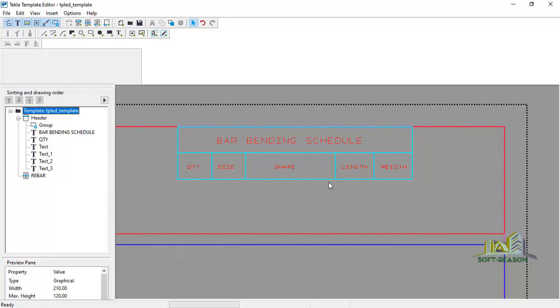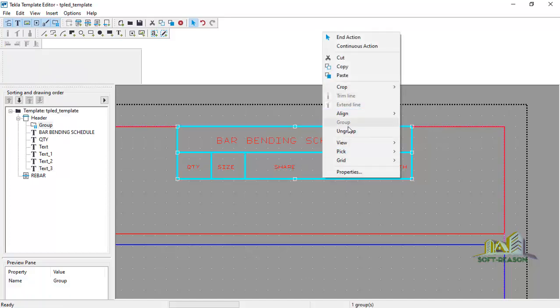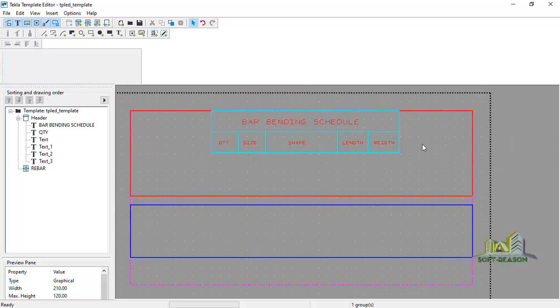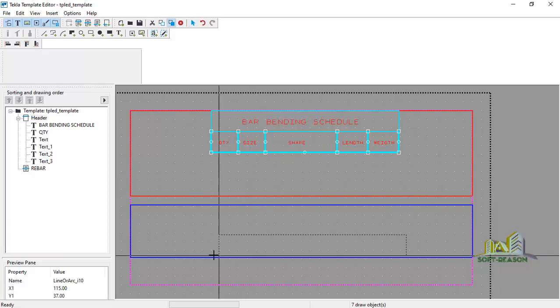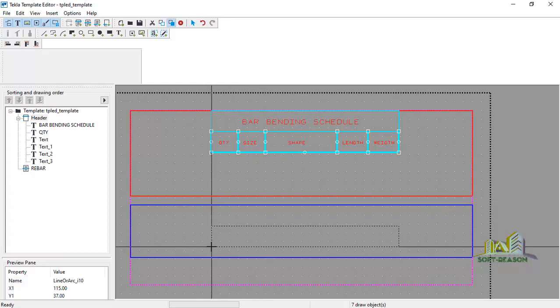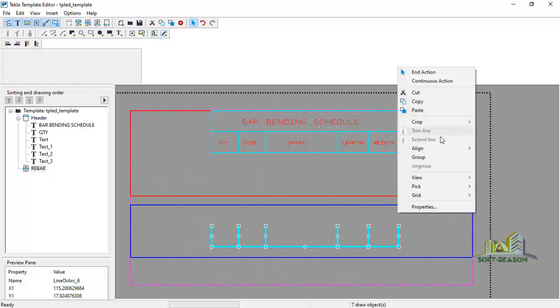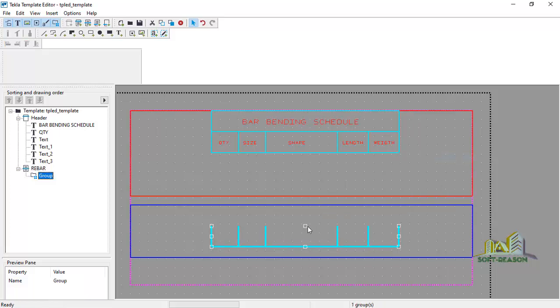All right, so after which select this, and then right click, click on group. All right, so we want to copy this to these other provisions. Okay, so we just select it like this. You can see the part of this is being selected. Right click, and then use copy, and then paste again. Bring it here, make sure it is in line with the one upward, just like this, and place it. Now this one being selected like this, right click, and then group it back again, so you can adjust it by pulling it up just like this. Okay, to have a bigger space just like this.